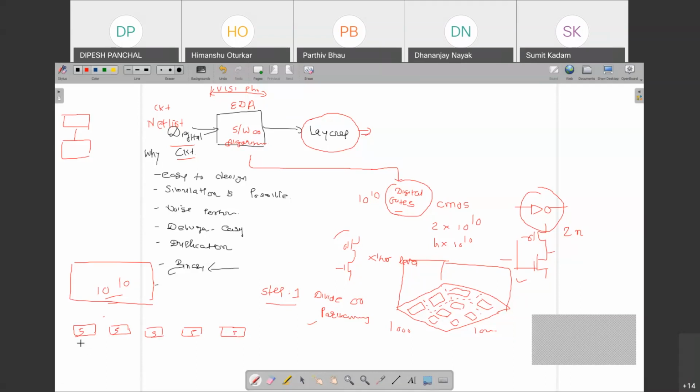Or if I have a size constraint, I can do unbalanced partitioning also. So depending on the requirements, I can do balanced partitioning or unbalanced partitioning. But the concept is that you first have to pass your design through this partitioning step. If you do the partitioning, definitely you have to work on only that small sub block or module.